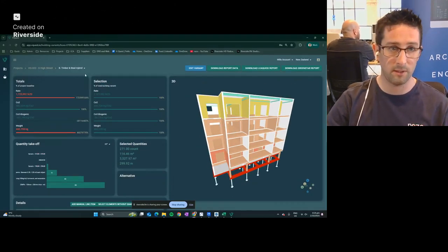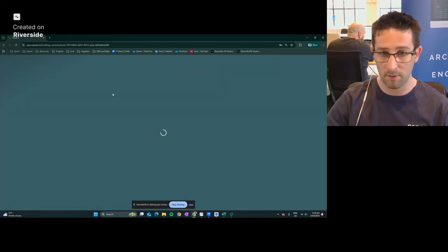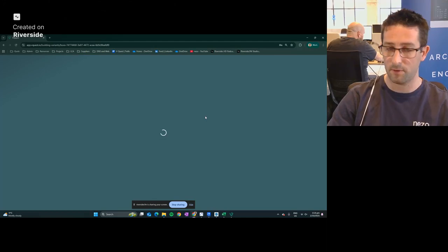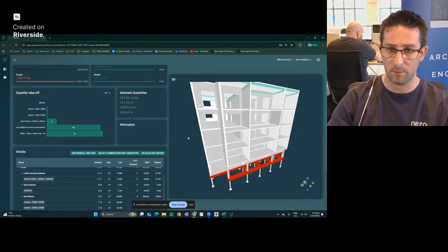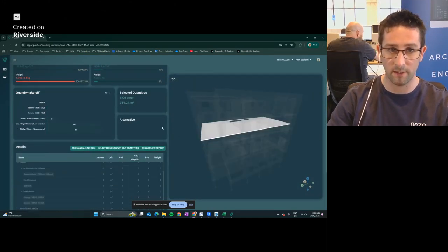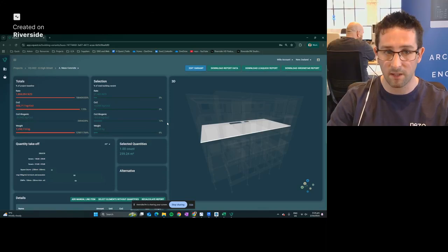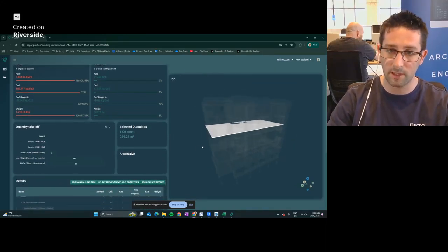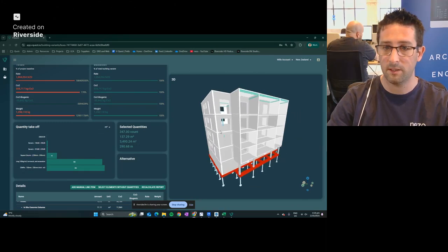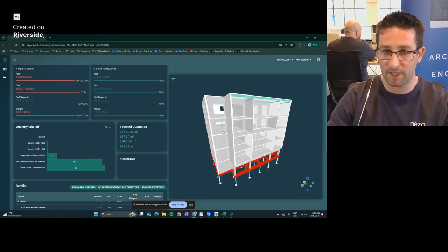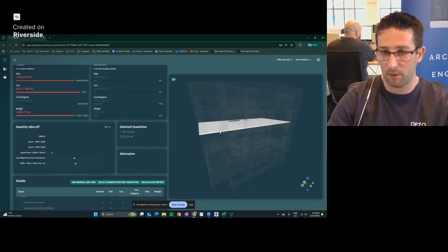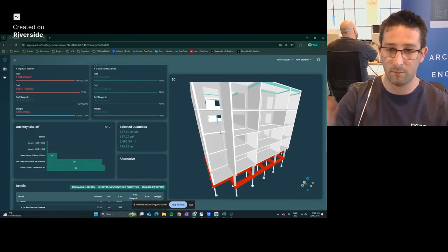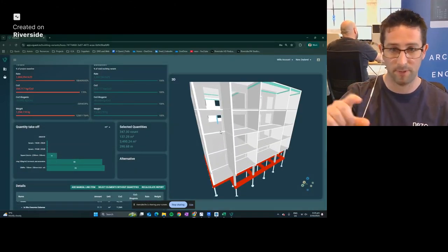So if I was in the build option here for concrete, and this is kind of an important example, so that model's loaded up. We have a concrete floor here. It's not terribly high in cost in comparison, but it does have high carbon emissions. So we want to quickly understand, is it worthwhile designing and investigating if we were to swap this out for CLT, for example? Now, the problem is this has been modeled at a 150 thick slab.